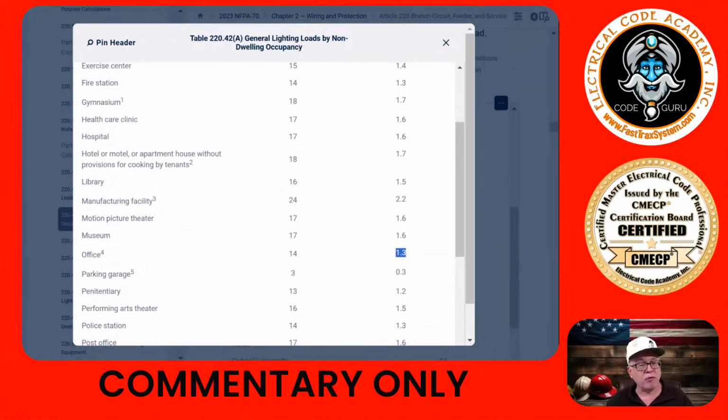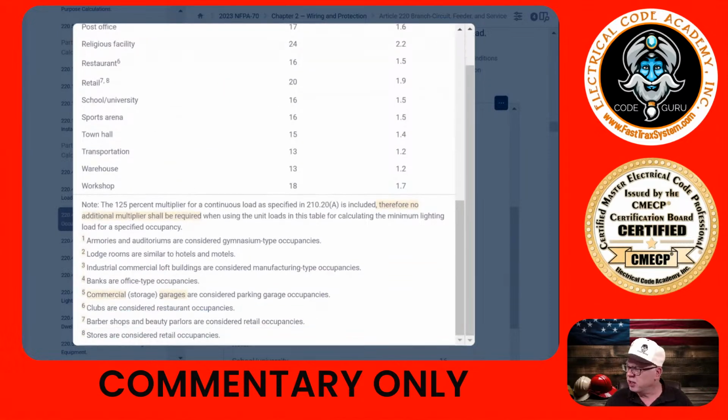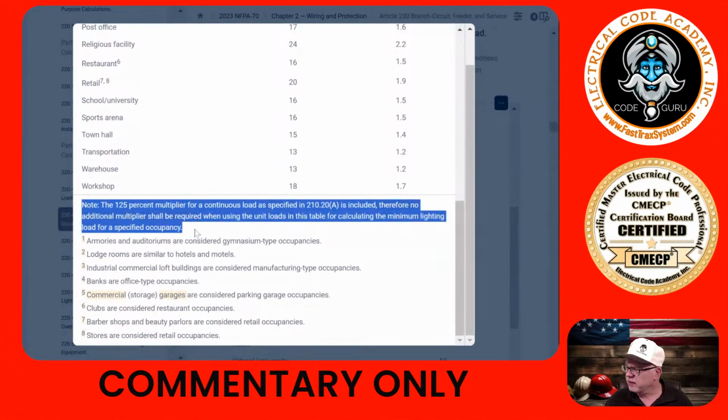Something interesting here: in the 2023 edition, at the bottom there's a note. This note is extremely important because it tells you that the 1.3 VA per square foot for office lighting is already figured in as a continuous load, so you don't have to do anything else for it. You just take that 1.3.